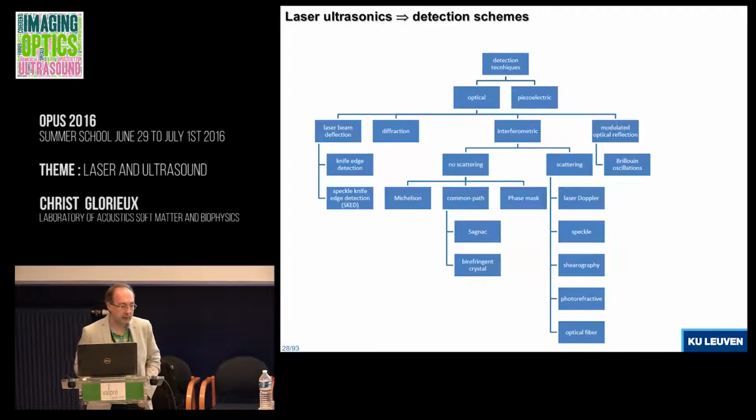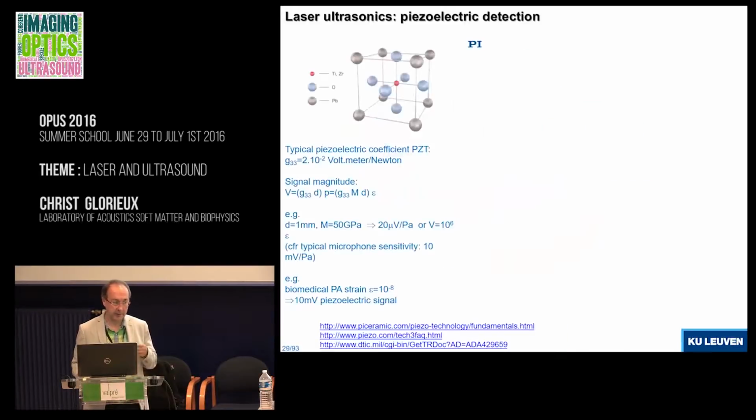And in electronics, measuring millivolts is not so big of a challenge. I think you can measure down to microvolts. So even for small strains you have quite some signal. That's why piezos are used in biomedical applications, biomedical photoacoustics, because the stresses are small. You cannot heat the body too much. So that's why you need a sensitive technique.